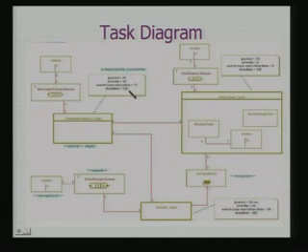Because this is an active object, I have indicated by this stereotyping that it is an active object. Since it is an active object, the thread corresponding to it should satisfy the schedulability constraints. So, you have specified the period, the worst case execution time and the deadline. These details have to be represented so that your specification becomes complete.